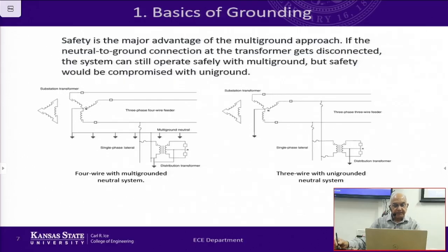This is connected to the neutral here, so phase and neutral. And the neutral is grounded right here. This is a small transformer, kind of mounted on the pole, maybe about 2 feet in diameter. Very small transformer. This serves about 10 to 25 kVA, so for 4 to 8 customers or something like that.